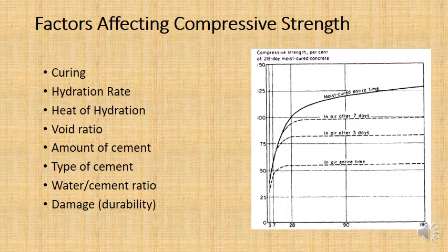And that will mean that the cement molecules won't have water to react with. So hydration rate is tied with curing. If it's got a slow hydration rate, then you need to cure for longer to make sure that there is water in contact with the cement molecules.